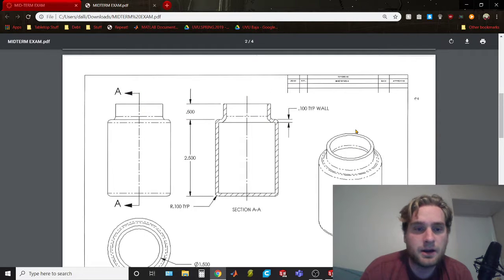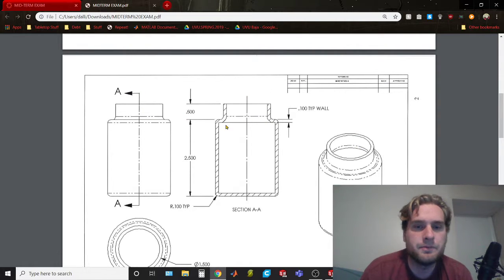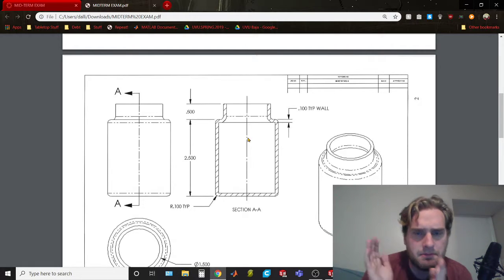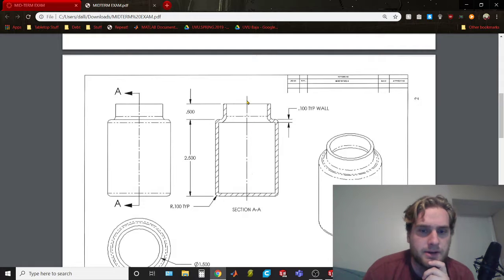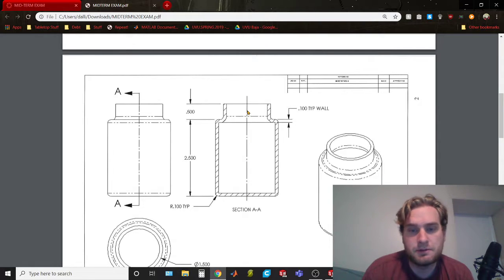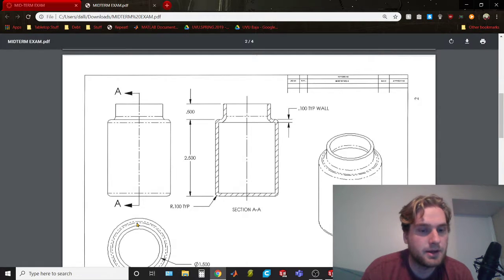So looking at our bottle, the very first part we're gonna do, we can see there's a section drawing right here. And two things strike me immediately as something we're gonna want to take into account. First, right here, this line of symmetry. We're essentially going to just do a revolved extrusion around that axis. That's going to be the central axis that you could spin that thing around, and that's how we're going to create this 3D object, since it has radial symmetry.